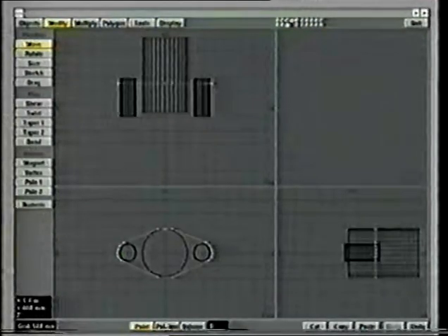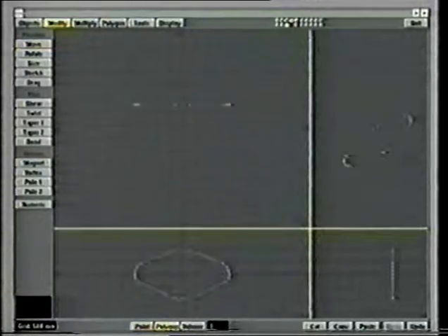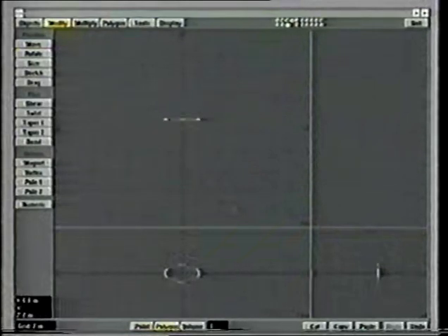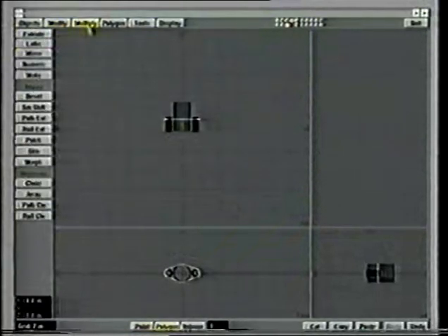to this point here. So the polygon is facing in the right direction, and I'm going to extrude it backwards down the ship, which is in the plus Z direction. Grid size is 2 meters, so I probably want to do it for about 5 meters.